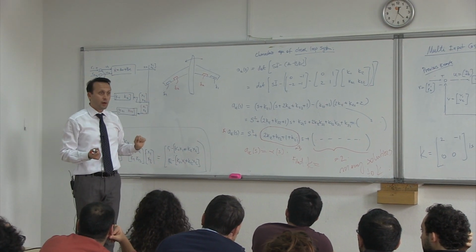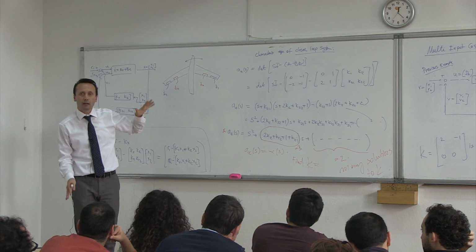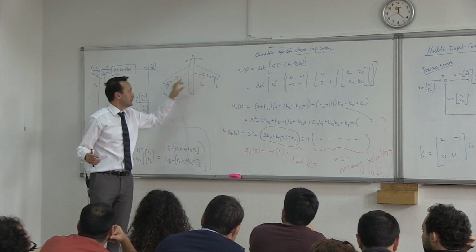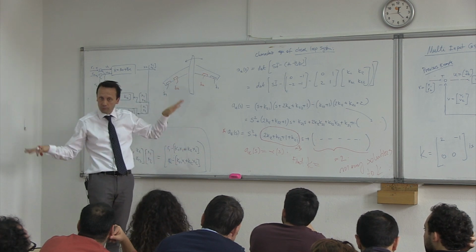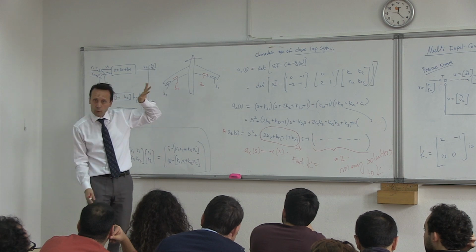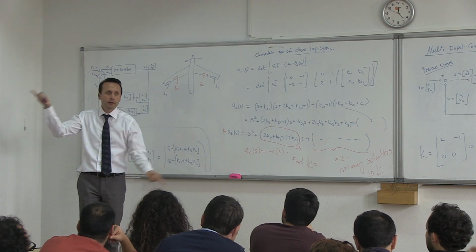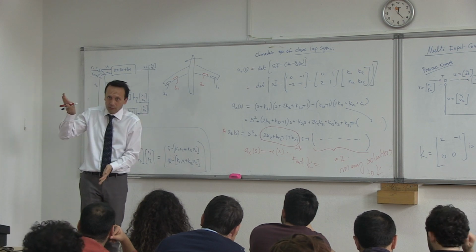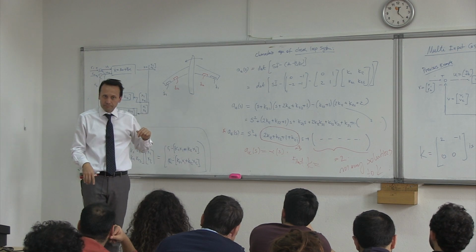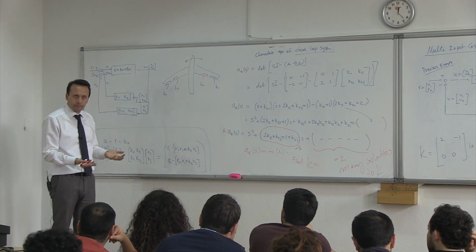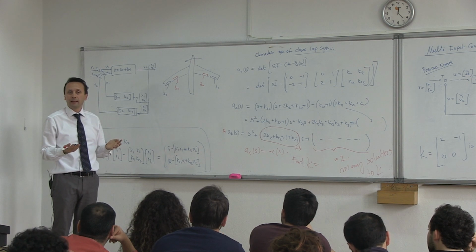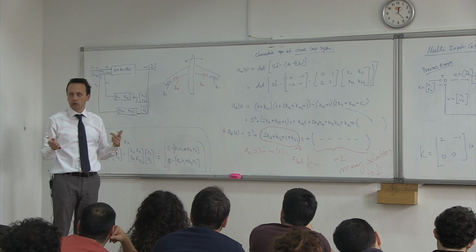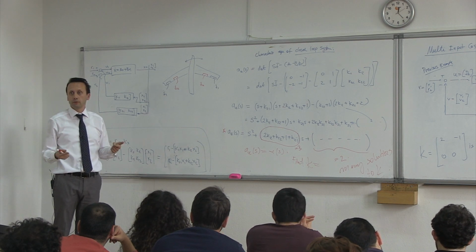But since you have the second one, you could now make much faster roll movements than previously, because if you didn't have them, you would only have these two, and you would have some roll moments. But because you have the second one, you have now much higher moments, and you can make much higher turns now, right? So now it's up to you. You want to have fast turns, or you don't need that at all. Basically, if you have more controls, you have more choices now. Okay? And you have to make an intelligent decision which one you would like to use. Okay?